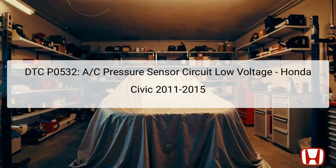The Diagnostic Trouble Code, DTC P0532, indicates a problem with the AC pressure sensor circuit, specifically low voltage. This sensor is critical for regulating the air conditioning system's operation by measuring refrigerant pressure, which informs the engine control module, ECM, of AC system health.